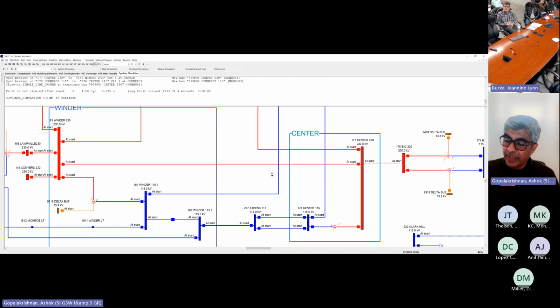Oh, that's good. And sometimes utilities will do it; normally N-1 is the standard, because once you go beyond N-1, it becomes harder to coordinate and achieve selectivity. So they may do the study, but they may not really mitigate the issues found, because you would have to spend a lot of money to mitigate. Then you have to make a decision: do I need to or not? That's there as well.